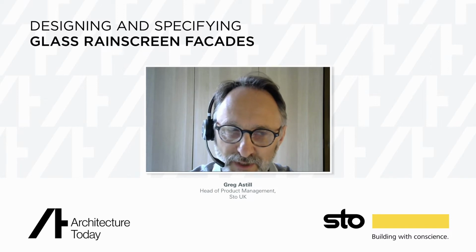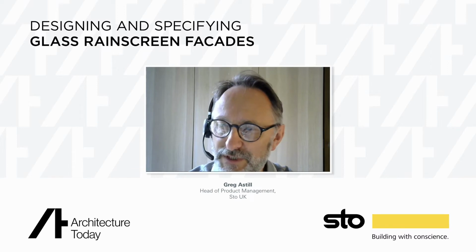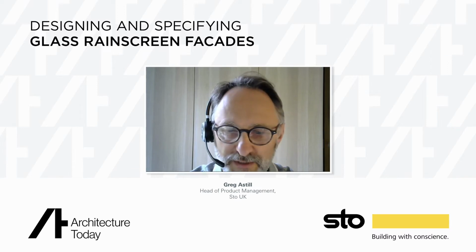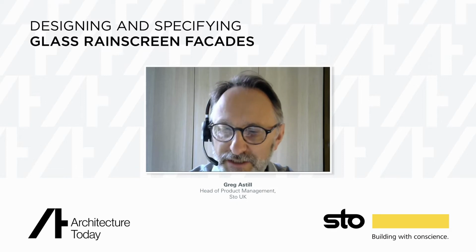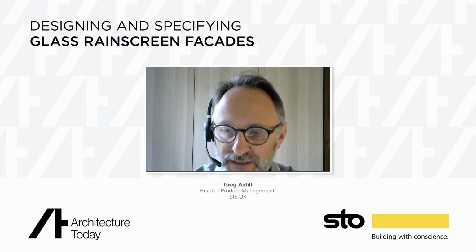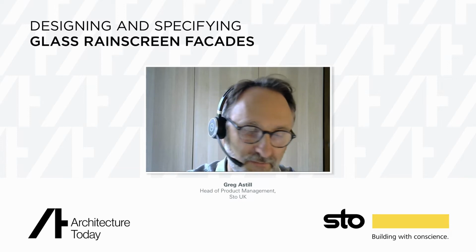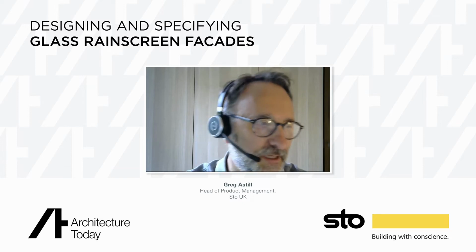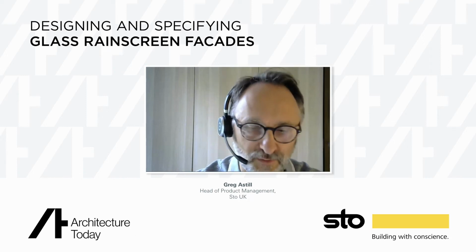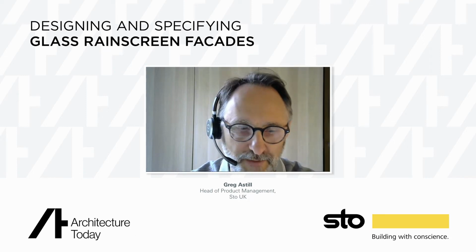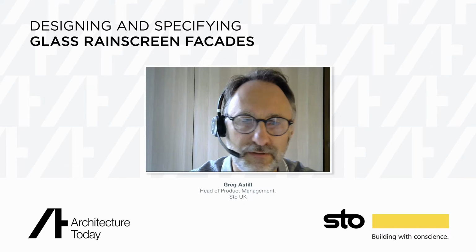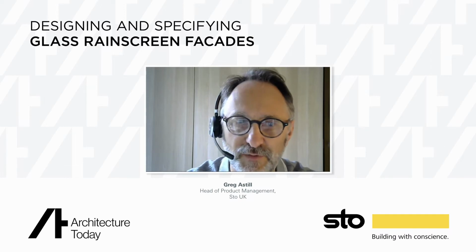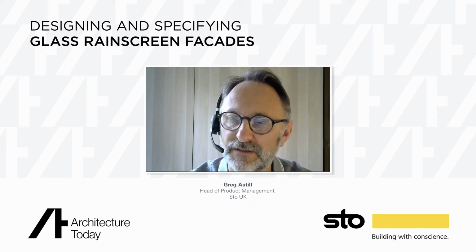When it's combined into the composite panel, which is what's tested, the EN 13501-1 test that is done, the fire classification, and all of the tests that go into building that classification, the product is safe for above, what's coming up is 11 meters, 18 meters currently, but next year it will be 11 meters through all the nations of the UK. So we don't use a different adhesive for low rise. No. It's the same adhesive and the same fire performance with every panel that we manufacture.